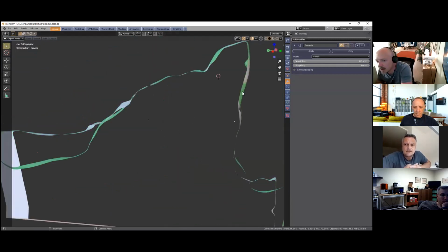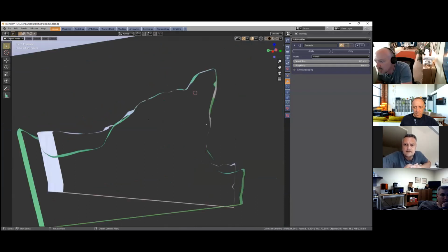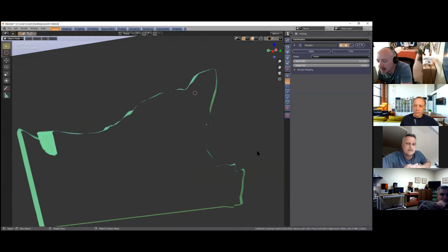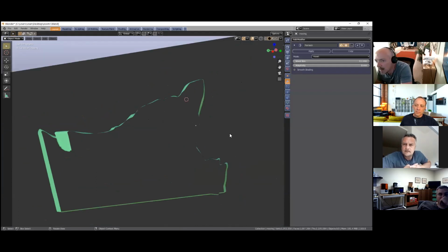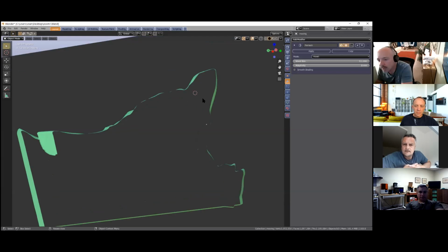So the remesh will get rid of the inside, all of the inside bits, which is absolutely fantastic. So I'm going to click on this, and it'll get rid of the inside. Can you see? All the insides removed. But when you do this, make sure you've got a very small size, maybe 0.1, because we don't want to destroy the integrity of our scan.